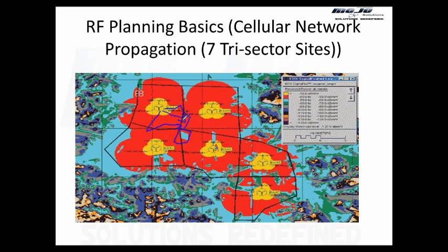All these signals are not interfering with each other. The interference will only be caused by signals which are intercell signals, transmitting at the same frequency. So this is not causing interference. This can increase the signal strength, or it can decrease the signal strength based on constructive and destructive interference. Usually multipath increases the signal strength, if we are not going through the phenomenon of multipath fading.